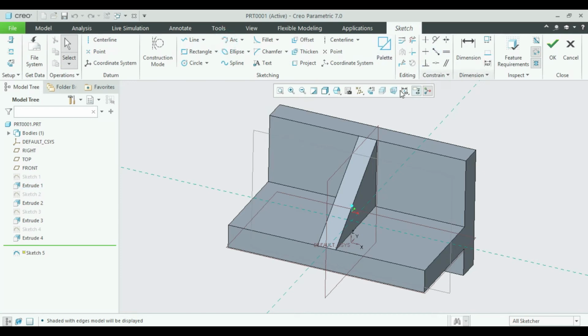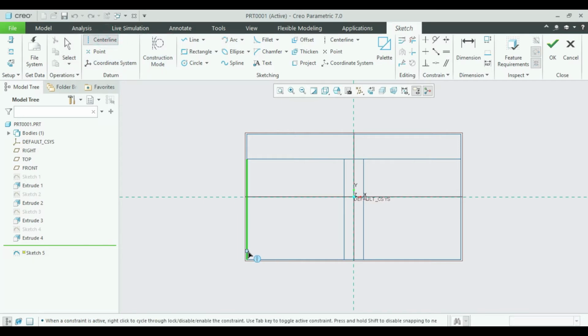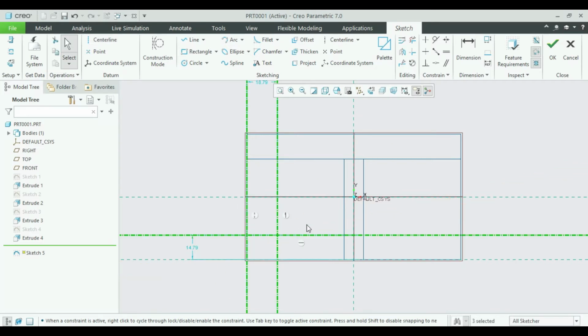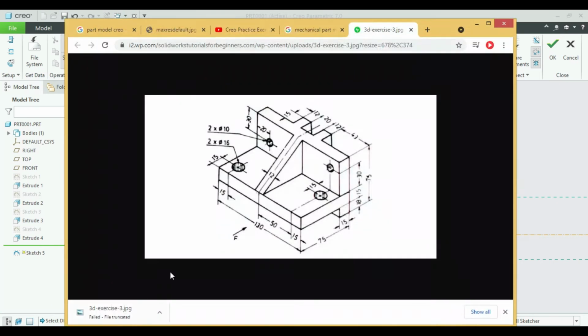Take plate, sketch, wireframe, right, center line, and again center line, one more center line. Yes, as we know that there is a 15 dia, so bring it down this dimensions 15 dia. When you press the center line, it is kind of an escape and also the done.